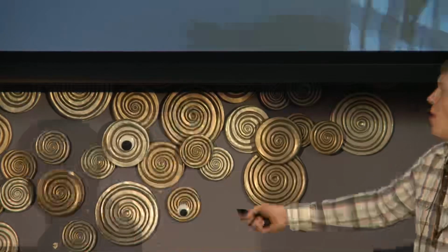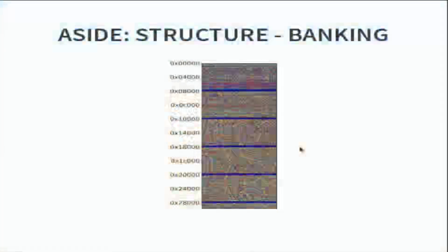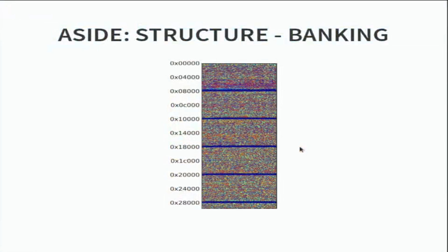And that shows up really, really well when you have a firmware file. For example, in this image that I'm showing you right here, you can see regular structure at power of 2 boundaries, and that's a real clear indication that whatever target you're looking at is using banking of some kind. A good heuristic is to count the number of zeros or Fs or repeating bytes right before power of 2 boundaries, and the lowest power of 2 that has that is probably the one that you're seeing banking occur at. But actually, these days compilers have gotten so good at allocating code in these situations that I had to sort of beat the compiler over the head to make an image that would show up here. So I recommend the heuristic method rather than visually.